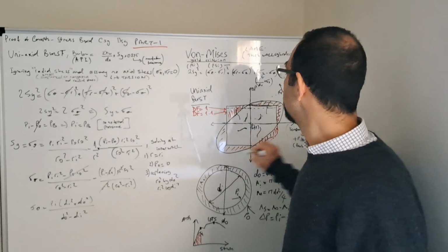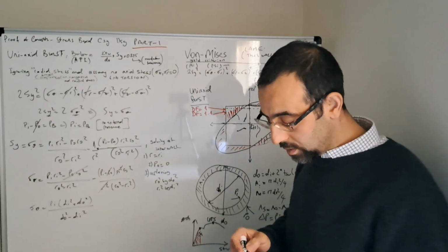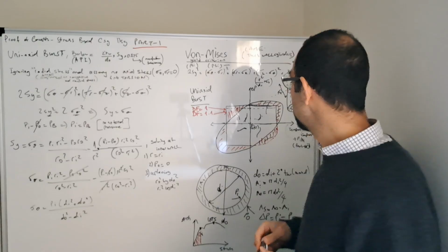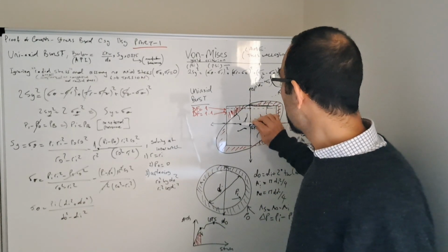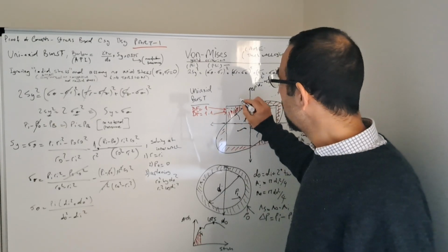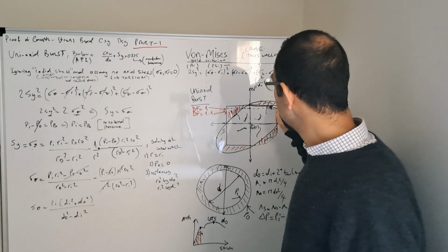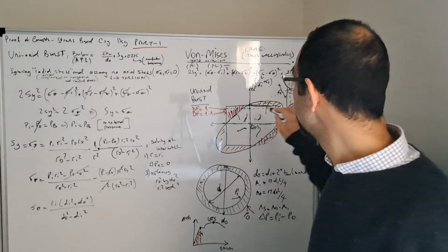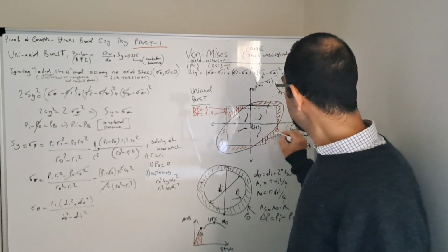And here we have the design limit plots. We are going to build a design limit plot in part number 5 of this video series. And today for the burst rating we are covering the upper part, right? The left quadrant here is compression and burst. The right quadrant is tension plus burst. And you can see that these are all the uniaxial limits.